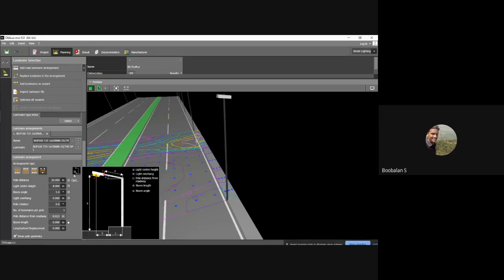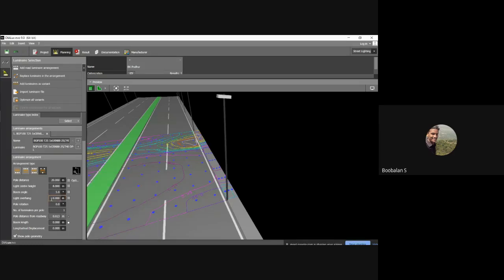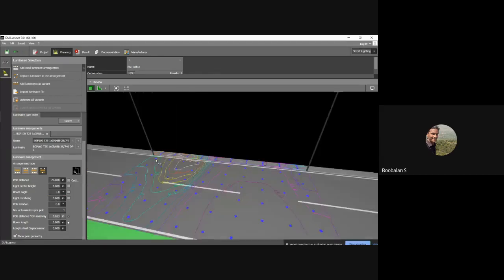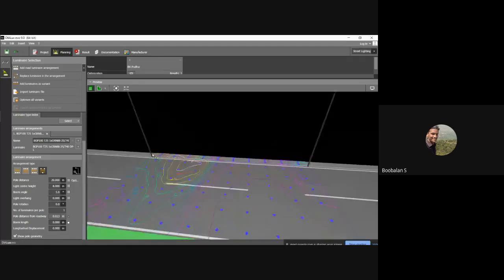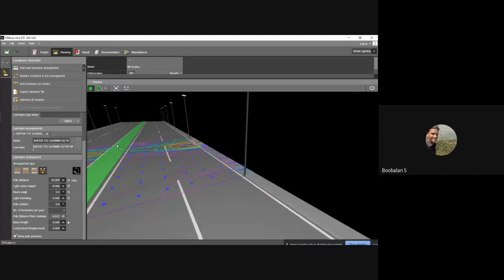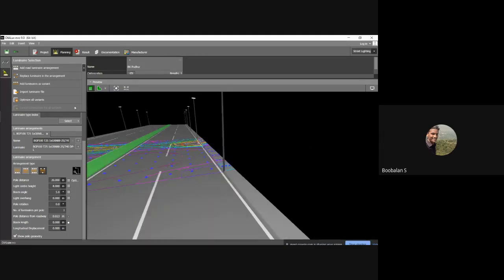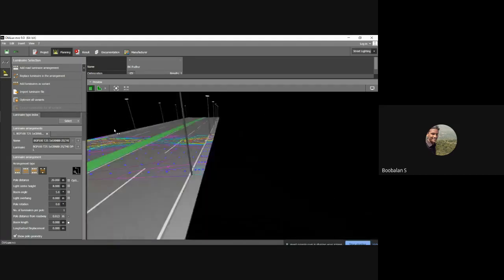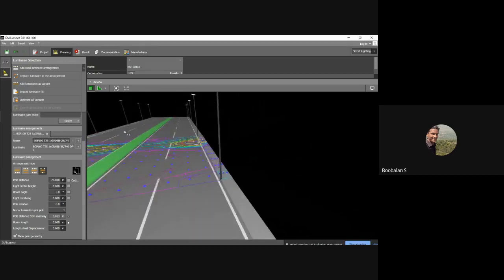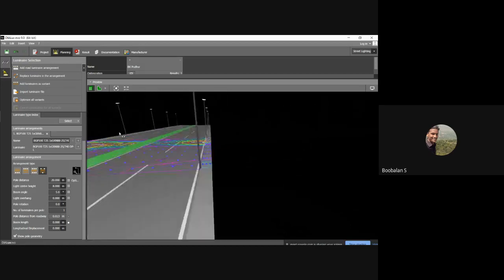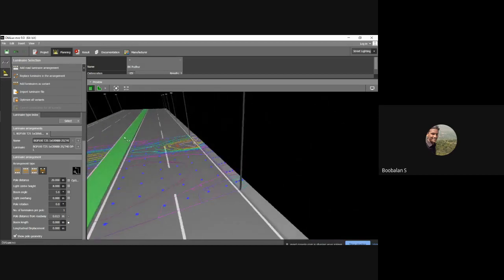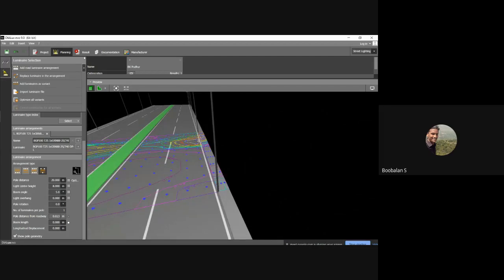So you can change this entire thing, right? So you can design your entire layout. Once you have fixed these things, you can calculate your light intensity level. How are we going to calculate the light intensity in lux? Now there is a function called Result. Once we have finished the light fixtures as well as the civil buildings, and everything is finished, go with the lighting calculation. This is the most important thing. Just click Result.